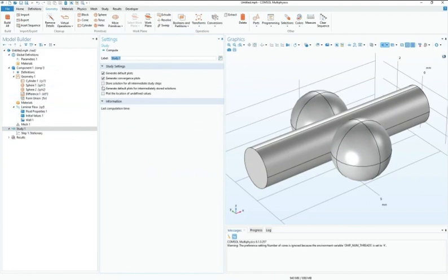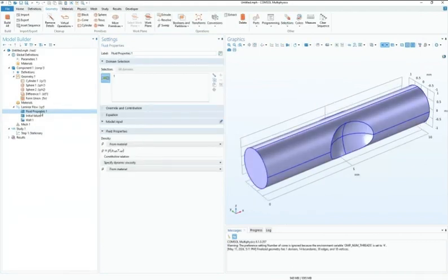And then yes, these are the fluid properties. Now we'll determine the fluid properties, which is usually blood. And in this case, we'll use user defined. And then for the viscosity, user defined, and then 0.004.